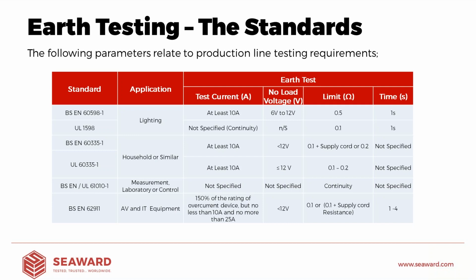Our limit can be 0.1 to 0.2 plus any resistance in the supply cord. Now, interestingly, for this particular standard, there's not a specified time level. The standard actually states that it should be performed for long enough for the measurement to be performed. So again, we typically say 1 to 2 seconds would be all you'd need to perform that.